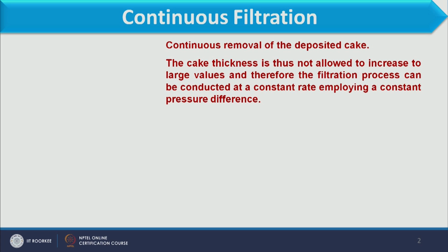As the thickness of the cake increases, the volume collected as filtrate decreases. So, that rate of filtration cannot be maintained. To maintain that rate of filtration we have to increase the pressure so that it can be operated at constant rate.